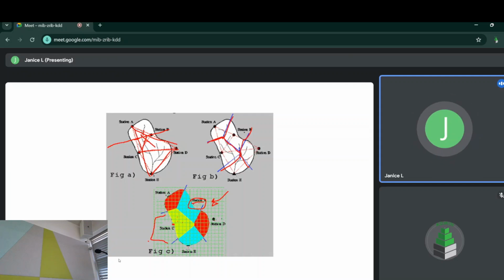Okay, and that's how you get the average rainfall. You're looking at, well, this is the amount of area dominated or dictated by each station, and that station recorded an average rainfall of that. You're doing a weighted average. Okay, and with that number, whatever number you get, that is the average rainfall for that whole catchment, that whole area. That's the average rainfall.